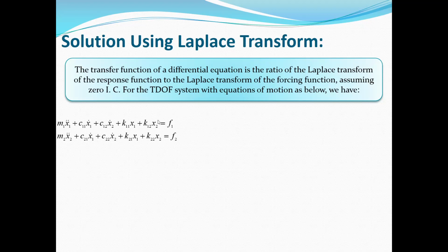Here, in this case, if you use the Laplace transform, you can directly find the particular response or the steady state response for the system. But if you want to extract the natural frequencies, be informed that this method is not suitable. I mean, you cannot obtain the natural frequencies or mode shapes.